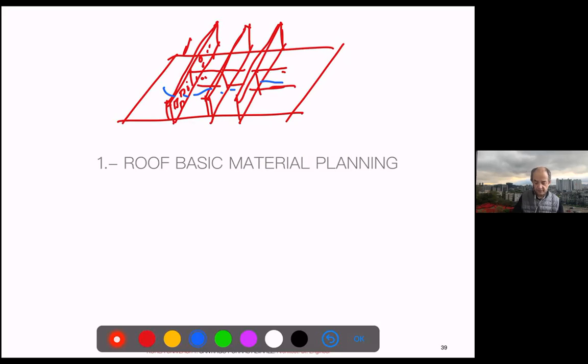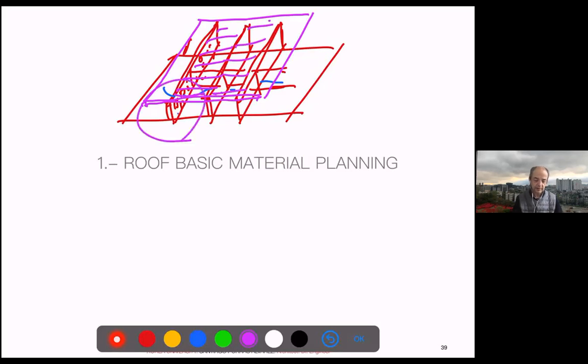And then over this layer is where you put that top layer, which you have distance enough to be able to do it with a kind of small vault or a small plate of ceramic or whatever. Now we do it with concrete. Actually, this technique is very used still in all the brick cultures, but there is nothing hollow beneath. So the base is always solid. The top layer is solid. You have just a porous supporting layer in between to let the air move. I don't know if that replies the question.